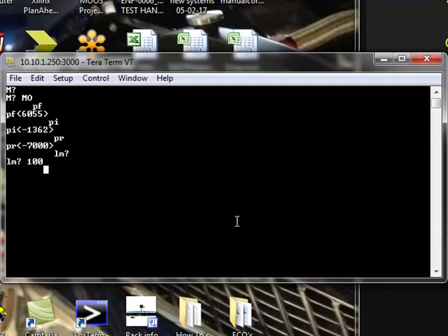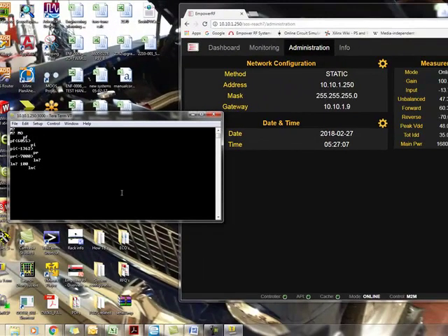So in this case, to set the gain, we use the LM between less than and greater than signs. We pass the desired set point. In this case, if we want to set it to 50%, we'll type in 50 and hit enter, and we'll see that the gain on the remote GUI is now showing 50%, and we can see the forward power went from our nominal 60 dBm to about 45 dBm.